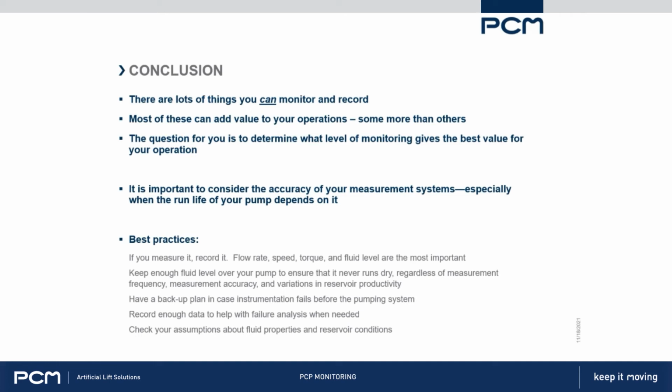It would be really nice if when they're doing a well test and they're getting that flow rate, that someone takes a fluid shot at the same time, so you have those two data points at the same point in time. So many times I get data from companies, and you can see you've got a flow rate at one time and a fluid shot at another time. Might not even be the same speed, but it seems that you never get a complete picture at one point. So I would recommend that if you're doing a well test, take a fluid shot at the same time so you have everything at one point.